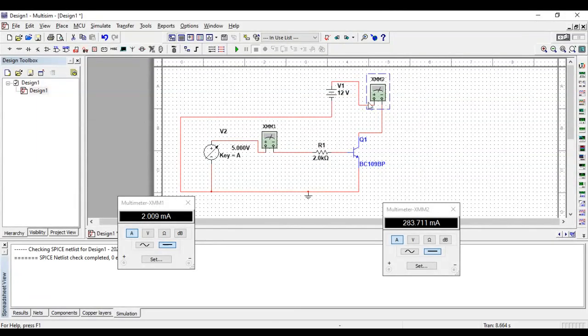As you can see in the circuit, you have a fixed 12 volt here. You can use the cable also, but you can fix. Let us have a look at the tabular form. You can open the manual and check the tabular form. Here you have VC 12 volt. You will change the base current, and you will take the corresponding collector current.